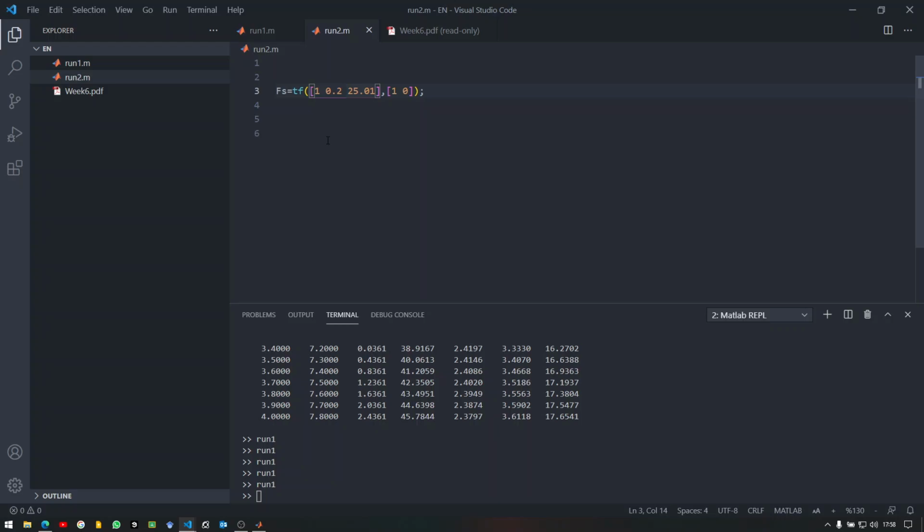So at that point, once I have the best possible root locus plot in front of me, then it would be easy to pick a gain so that my controller structure is fully known. And the strategy here is to use pole zero cancellation. Since there's a complex conjugate pair here, I cannot cancel the poles individually.